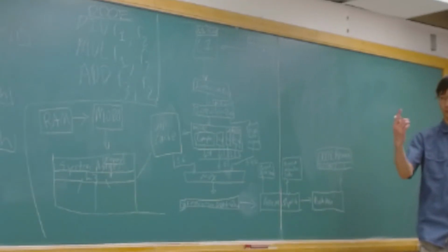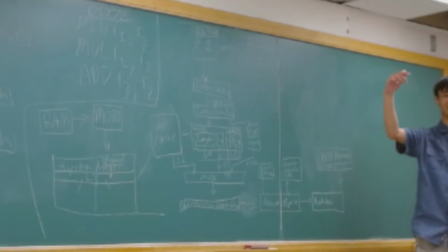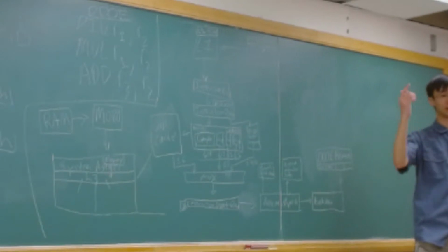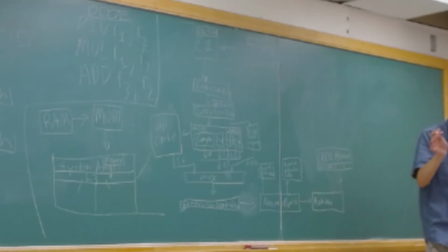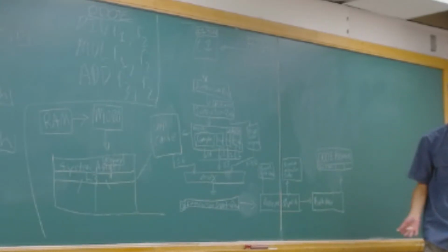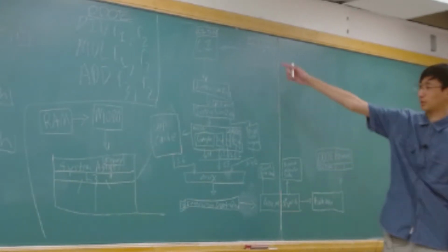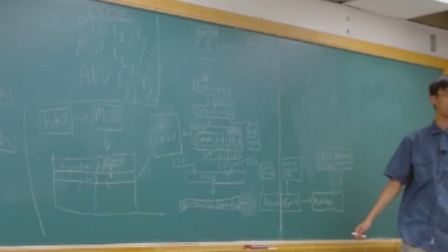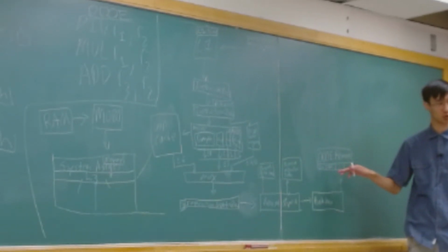And you can have multiple registers get operated on at the same time. So you can run a vectorized add, and that will add all the registers at the same time. It's not a crazy thought. You can do less work in the rest of this humongous thing to send one instruction to do 4 things at one time, and that's where they get stored.